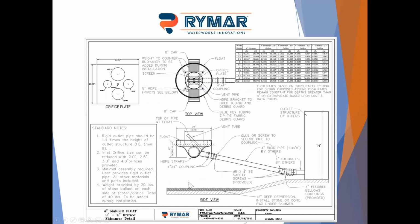A couple of things to note about our detail. We have a new flexible coupling. If you're familiar with a Fernco-style coupling, we've got one with bellows in it that we use for all of our products now. So it provides a little over 90 degrees of flexibility side to side or up and down. All of our skimmers come with an orifice plate that goes in the skimmer, and I'll show a little more detail about how that works later. And again, all of our skimmers have the open, full-size skimmer or the standard orifice flow rates on the detail.